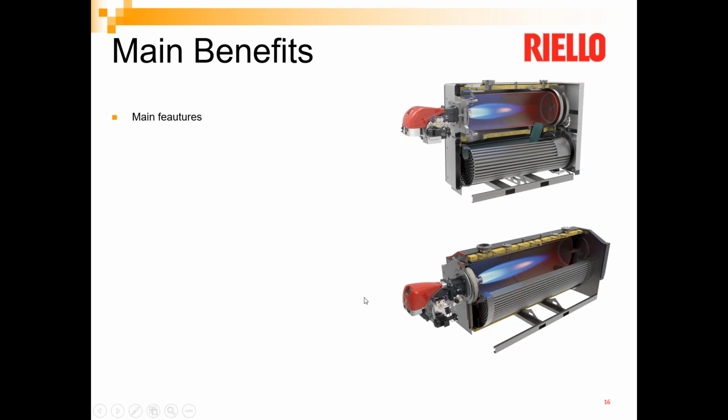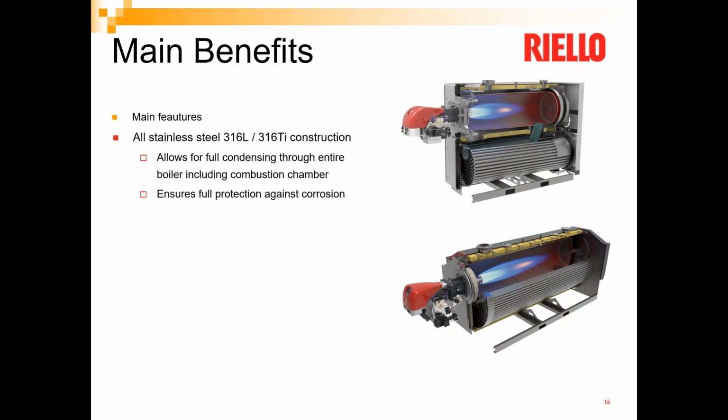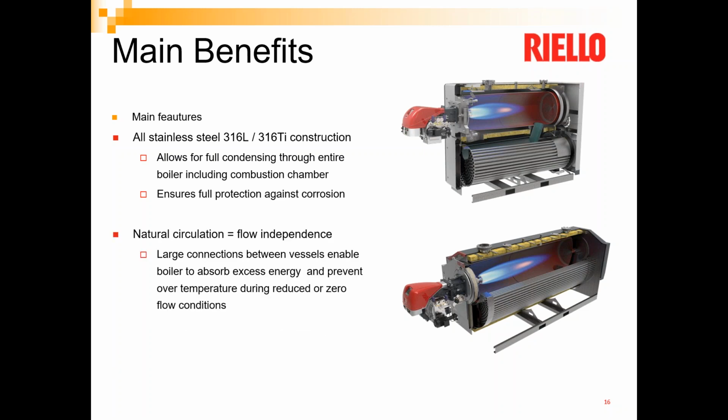Other types of Firetube boilers out there, which are coming out now, are one that we represent from Riello, which is a horizontal stainless steel condensing Firetube boiler. This boiler is above 88% in efficiency, and it's condensing, recovering that latent heat by turning that water vapor back into water and running it out of the boiler as condensate.